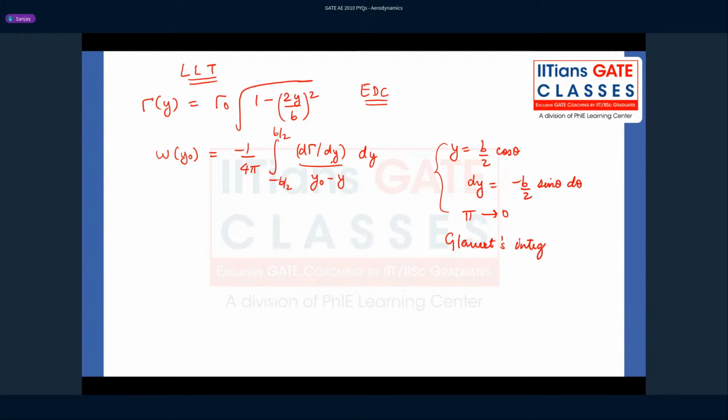Okay, you have to make use of Glauert's integral. Glauert's integral is a very special integral which helps us to reduce complex definite integral forms. It will help you to solve this integral quickly. So you have to make use of this and then integrate this. When you integrate, you will get the downwash as minus gamma naught by 2b.